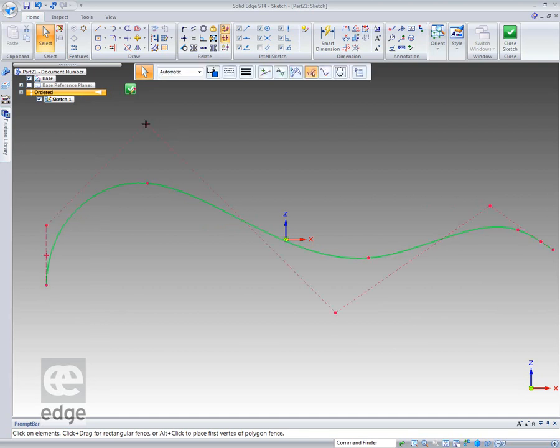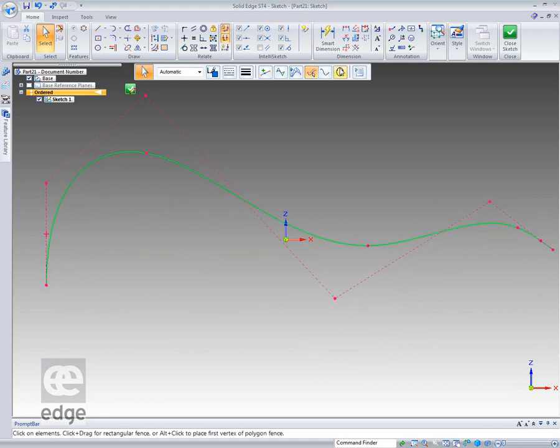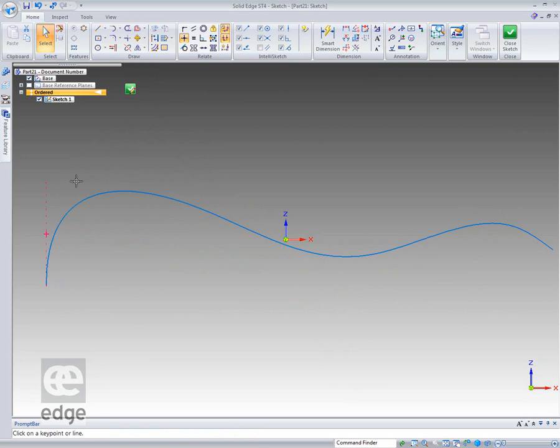I might then want to give that more strength, raise it up, and then I might want this one to be flat, so I could have this effect. Let's change that to local edit. See the effect there. I want that to be flat, so I'll put another constraint between those two, horizontal vertical constraint from that control point to that control point.